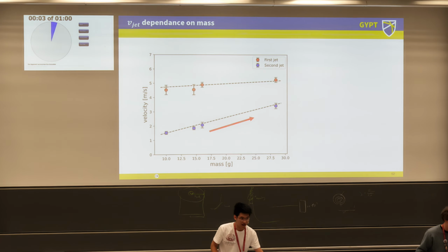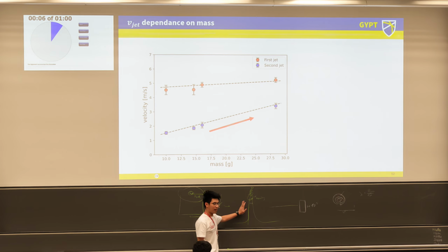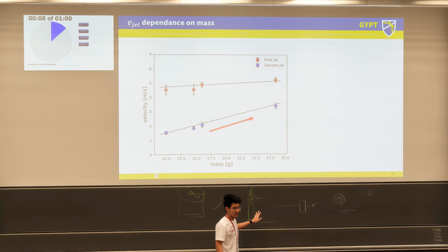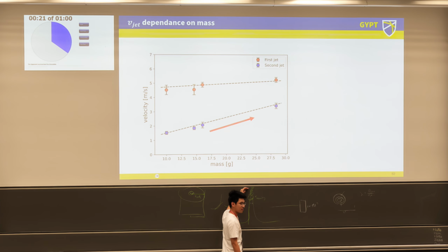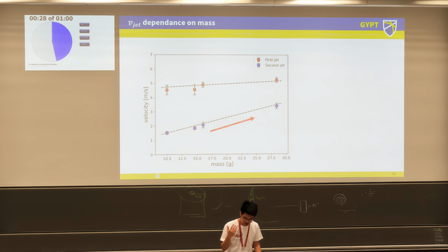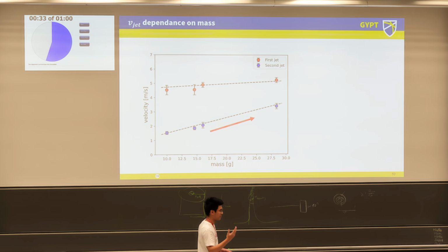So firstly, we clarified a lot about the jet height, because personally I believe that the Rayleigh-Plateau instability must actually be modeled in this case. It measures how the radius of the jet gets too thin, and that means the water will be divided into a few droplets, and therefore it might significantly increase the height because the momentum from the water jet focuses onto the small water droplets. So we definitely believe that this should be modeled in some way inside the simulation and the experiment in general. And secondly, we also